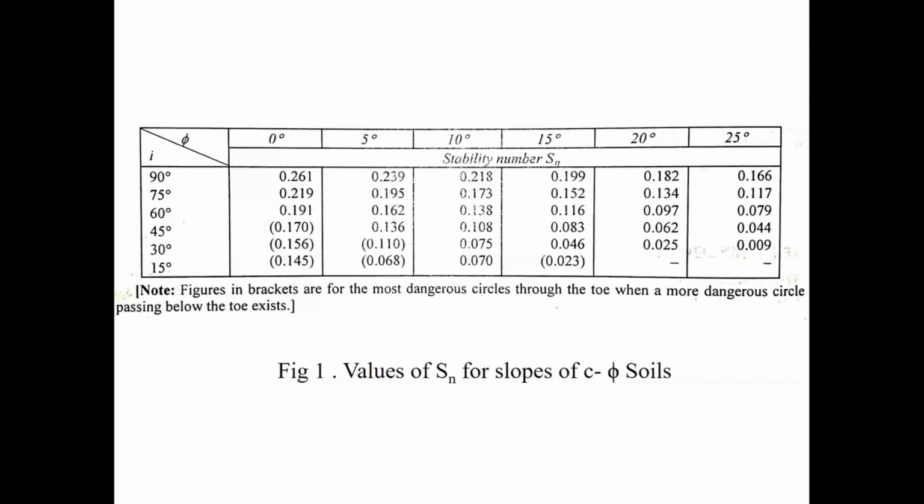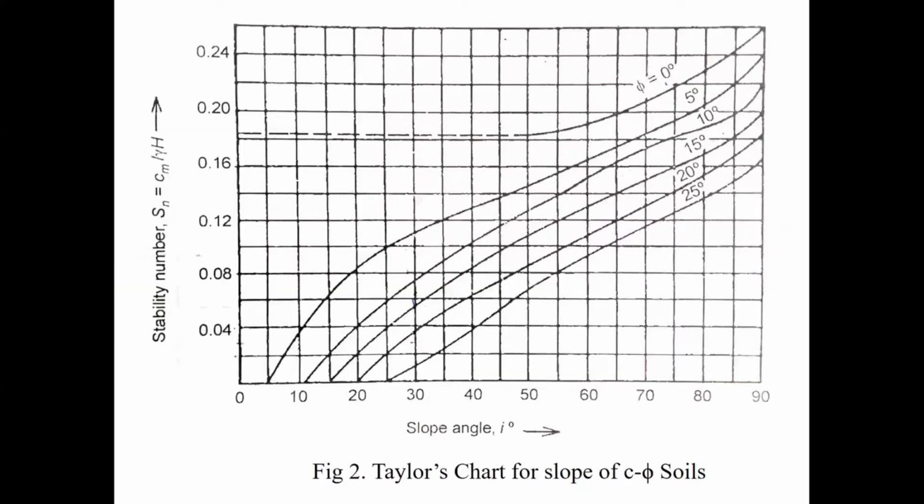Now can you correlate that idea now? How the Cm and slope stability are correlated? Can you imagine now mobilized cohesion? I hope so, because you can see that the soil has a cohesion of 200 kilonewton per meter square, but at this slope angle, only the cohesion of 18.9 has been mobilized yet, isn't it? The stresses developed have mobilized only 18.9 kilonewton per meter square. So you can go much steeper for that slope, isn't it?